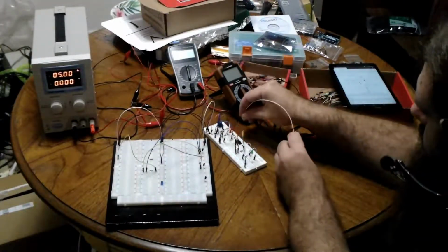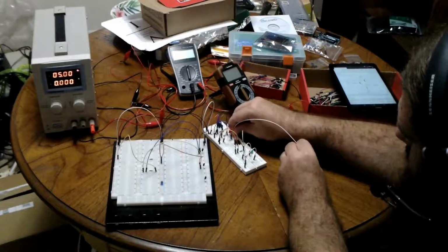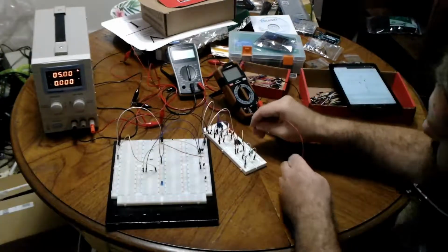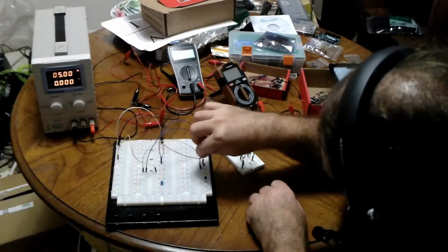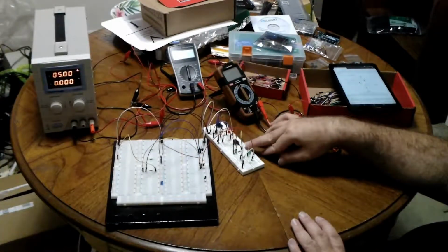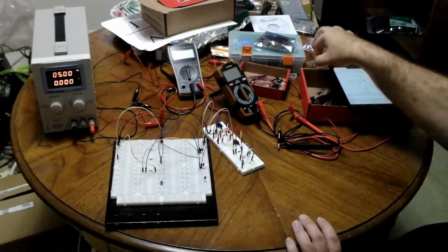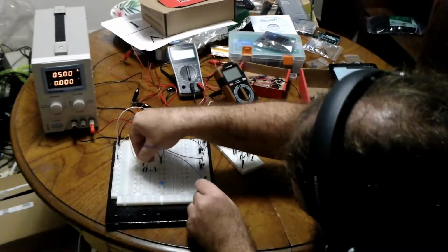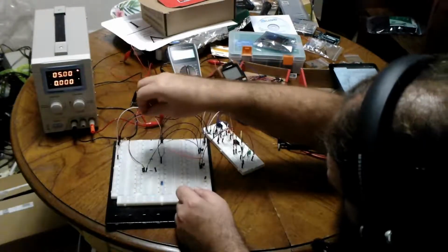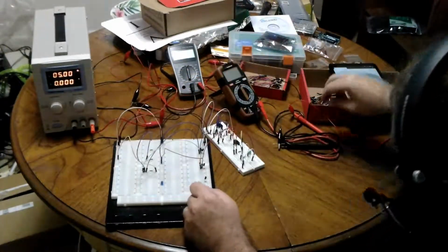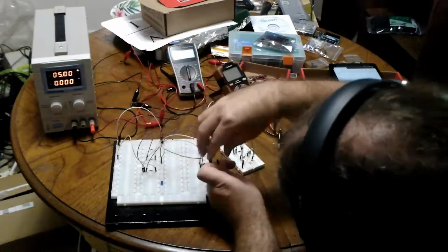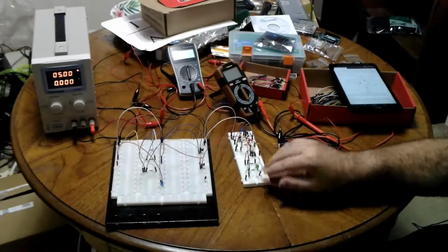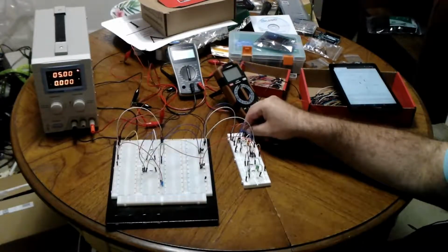We have our input 1, if this breadboard won't suck too bad, which, oh my goodness. So input 1 is going to be the base connection of one transistor. Input 2 will be the base connection of the other transistor, which is safe because we have these going through resistors. And you can see both switches are off, assuming no wires are loose. And then the output is similarly measured before the resistor down here. So we'll put this through a separate resistor for the LED, and that resistor goes to the LED and to negative power over here. And that measures our load. So right now, either it's broken or it's working fine because neither is on.